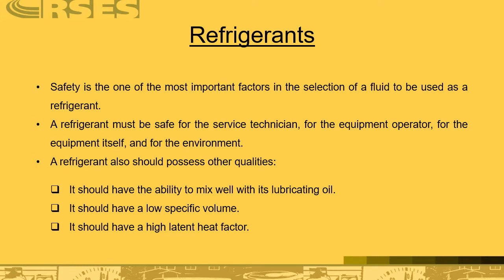Safety is one of the most important factors in the selection of a fluid to be used as a refrigerant. A refrigerant must be safe for the service technician, for the equipment operator, for the equipment itself, and for the environment. A refrigerant should possess a lot of other qualities. It should have the ability to mix well with its lubricating oil. It should have a low specific volume, and it should have a high latent heat factor.